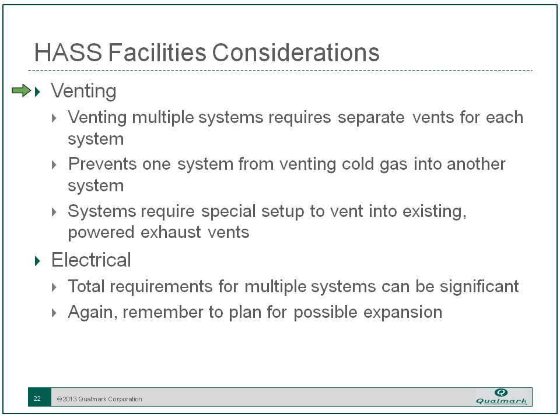In venting, if you've vented HALT chambers before in your facility and your facilities man is familiar with that stuff, then you won't be surprised. But it's different than the typical venting that you think of. You've got a cold gas under pressure being vented out only during cold cycles. And so if you have multiple systems, you can't tie them all together into the same vent line, because one system will pressurize the other. And even with dampers in place, if you have 2 venting at the same time, then there's more pressure to overcome for the second one, and you'll have more pressure inside that chamber.